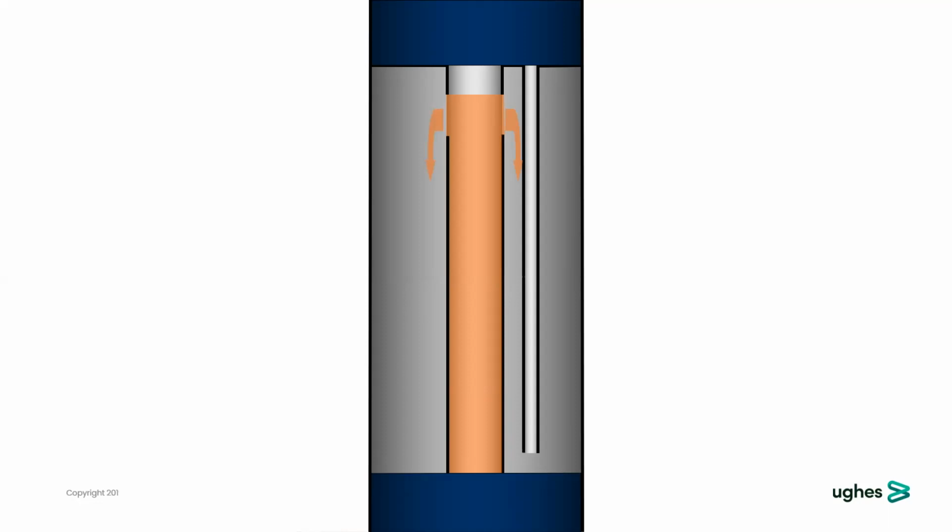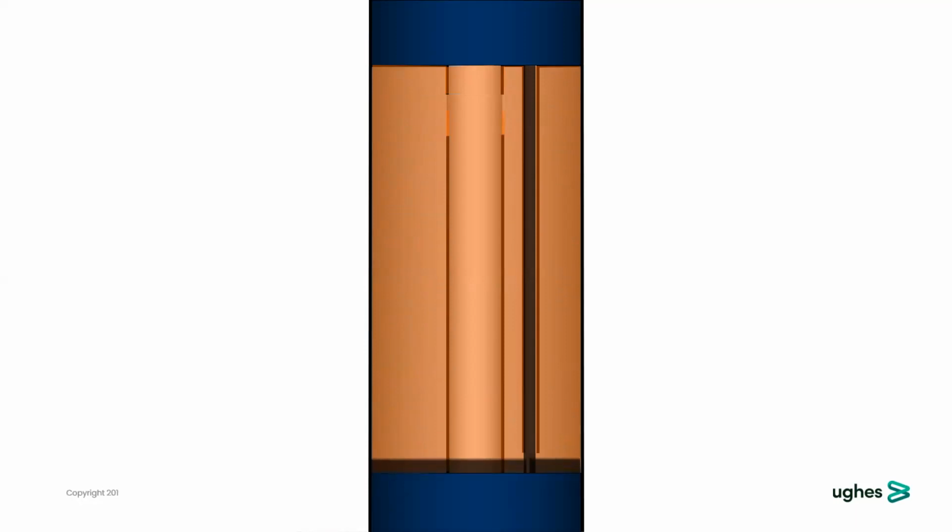So all of that is well fluid. This is the lighter one, while the heavier one is the dark fluid, which is the well fluid. Because of its higher gravity, it goes to the bottom. So you keep the lighter oil, which is the main fluid for motor and seal, away from well fluid. It's all about the gravity separation.